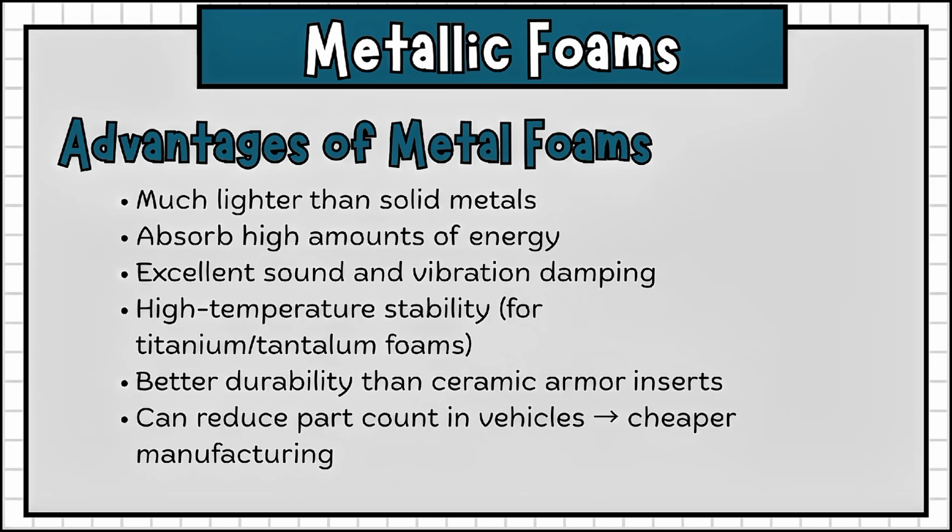They are much lighter than solid metals and can absorb large amounts of impact energy, making them effective for protection and crash-related applications. Their porous structure provides strong sound and vibration damping, while titanium and tantalum foams maintain stability at high temperature. They are also more durable than ceramic armor inserts, which can crack easily, and they allow manufacturers to reduce the number of parts in vehicles, lowering production costs and improving performance.